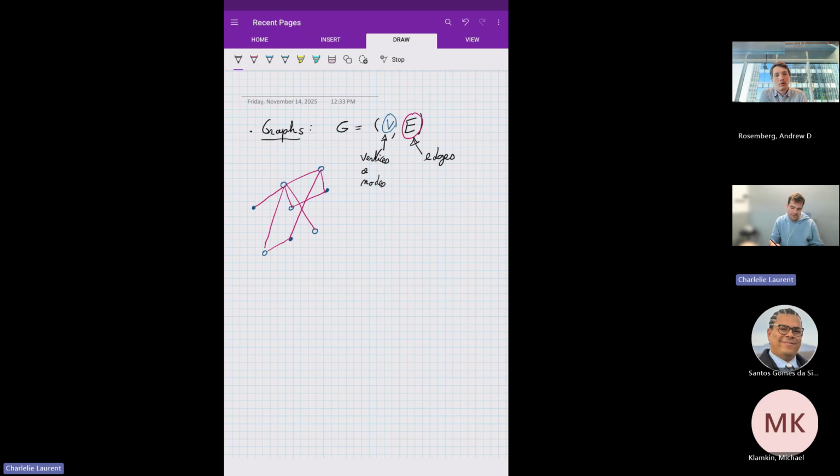Usually their meshes are unstructured meshes. I know that there are methods using structured grids combined with octree methods, or immersed boundary methods, or cut cell methods. So it's basically some tricks to still be able to use Cartesian grids, but the majority of people in industry, for industrial problems, are used to using unstructured meshes.